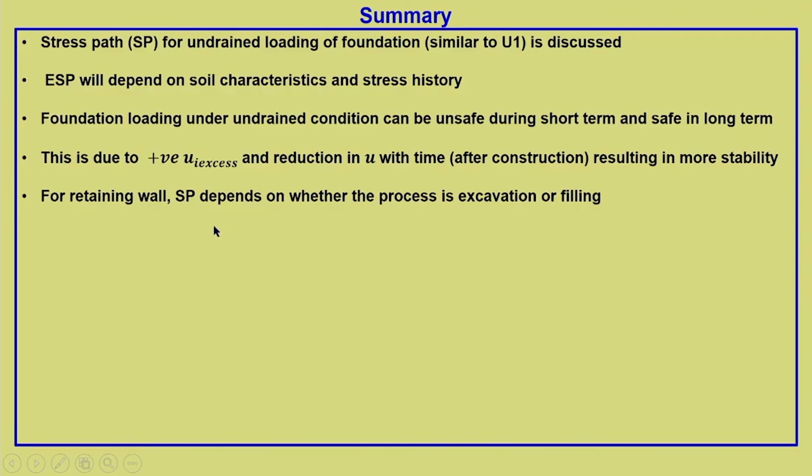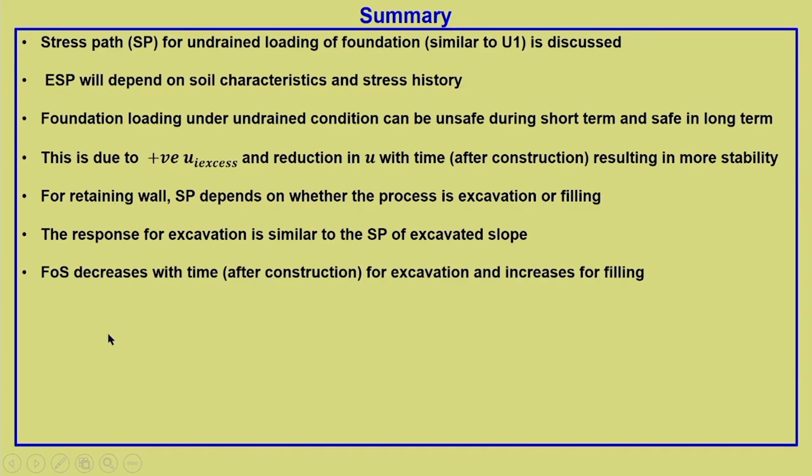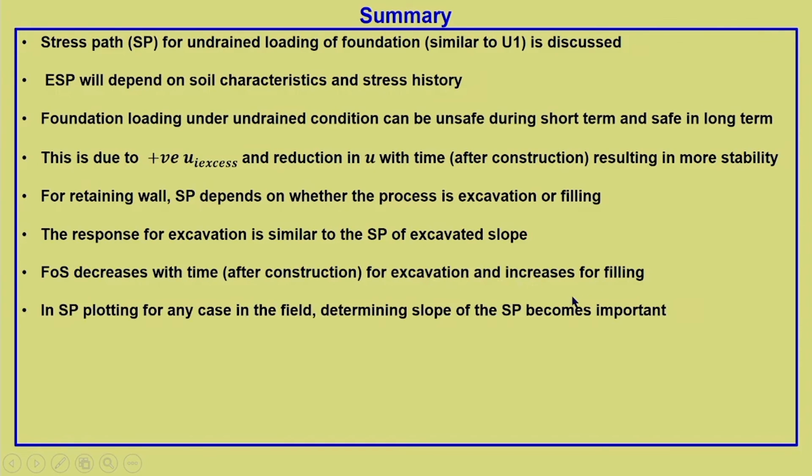For a retaining wall, the stress path depends on whether the process is excavation or filling. The response is totally different in both cases. The response for excavation is similar to the stress path of an excavated slope. Factor of safety decreases with time, that is, after construction for excavation, and it increases for filling.